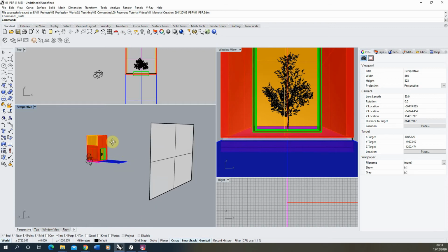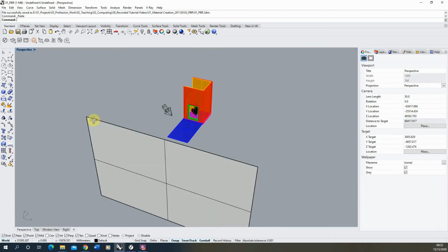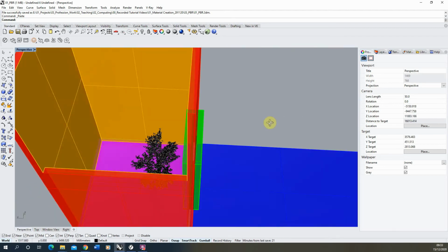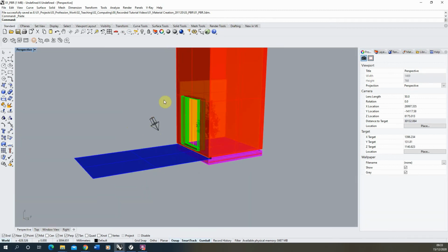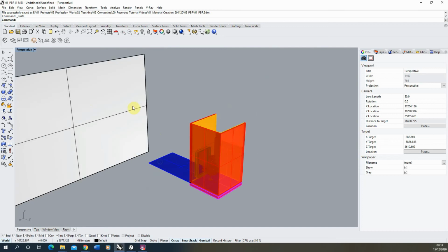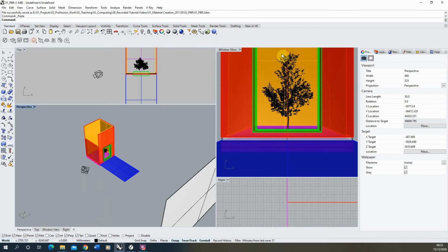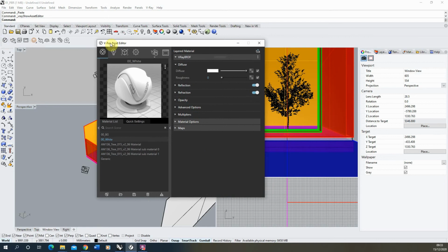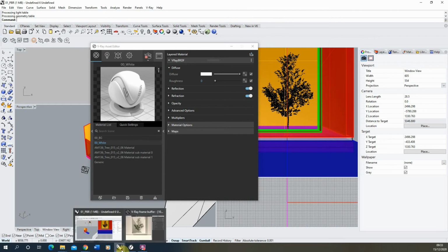real-world materials and effects. Now for this tutorial I've made this simple model here, which is just a simple courtyard. We've got a tree in there, we've got sunlight set up, so we just have a simple directional light, and I've got this background plane here with a texture on just to give us any background reflections to our scene. I've also set up a camera, which is this window view, and what I'll do now is open up the asset editor and open up my render preview, or my interactive renderer within V-Ray, just to show you what the scene currently looks like.